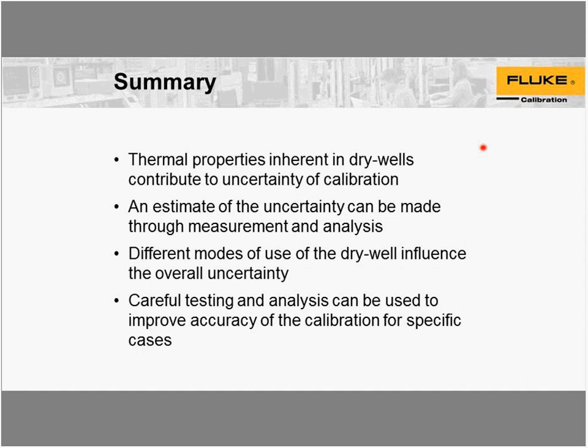We can evaluate the thermal properties that are inherent in dry wells by this method. We can come up with values that we can apply to our calibrations. We don't guess. We don't have to go by the uncertainties listed by the manufacturer, which may vary depending on the conditions.